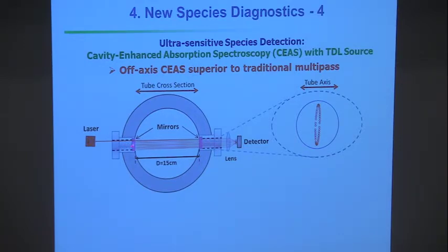But in a shock tube, when you pass the light in, typically through a window, as it goes across, it's usually deflected a little bit by boundary layers. And so typically, in a multi-pass cell, what happens after a few passes is that you can't get the light back out. Typically, the mirrors will have an entrance hole, and everywhere else it's highly reflective. And they'll have an exit hole, and everywhere else is highly reflective. So you come in through the hole, bounce across a few times, and go out the exit hole. Well, by the time you've done 6 passes, it doesn't hit the hole anymore.